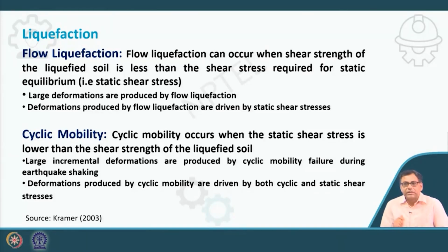So in flow liquefaction, cyclic stress reduces the strength of the liquefied soil but the deformation is driven by the static shear stress, while in cyclic mobility, the deformation is driven by both static and cyclic shear stress. Large incremental deformation is produced by cyclic mobility failure during earthquake shaking. These two cases follow the same definition that I have given.